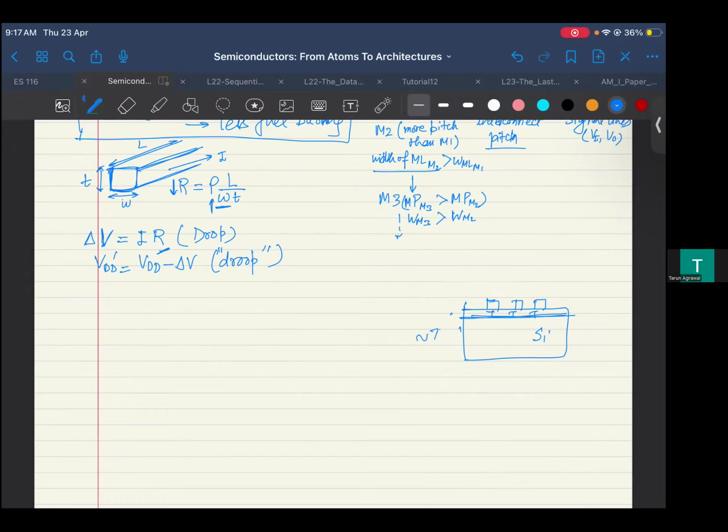The silicon. So what can I use then, if I'm using this to connect signals, whatever signals I'm using, connecting all of these lines? For power, is it possible that rather than providing it from the top, I can provide it from the bottom? So that means if I have the VDD which is going like this, then the VDD can go to this transistor from the bottom.